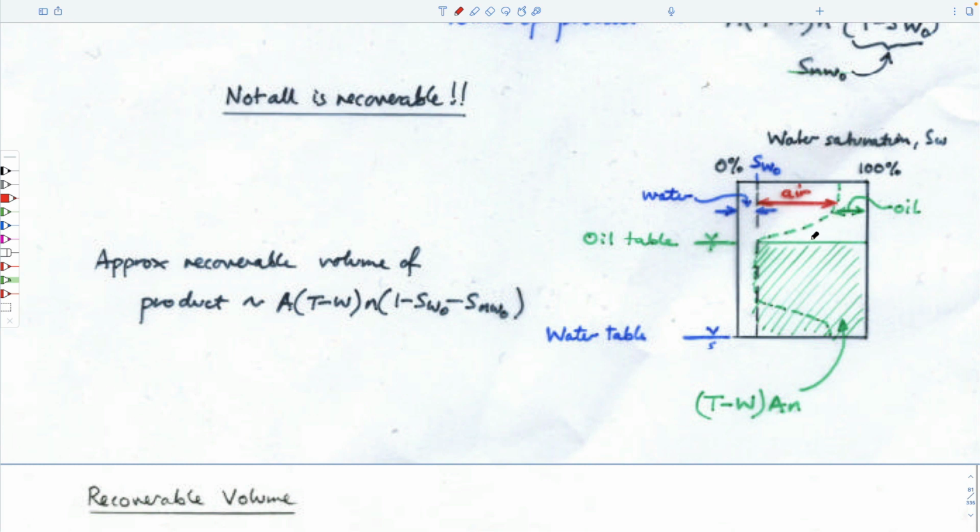Once we get below the chimney, we're sitting in this puddle of non-aqueous phase liquid, and that puddle is on top of some water and some air that's trapped above it before we go into fully water below this zone. And so what we could do is try and simplify this by just saying that maybe if this is the true thickness of our lens, which we've called W, then we can calculate the amount of NAPL that we have in the system just by drawing it out.